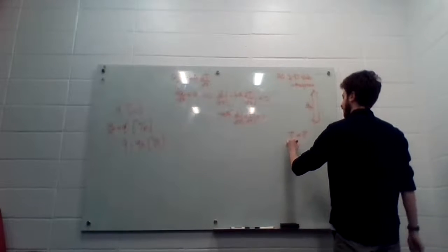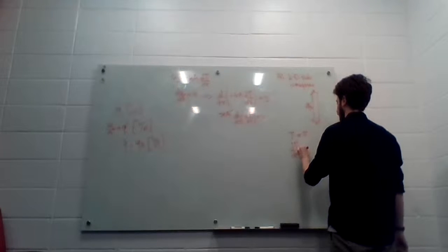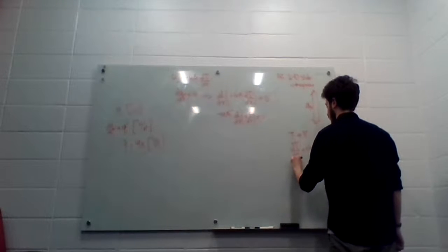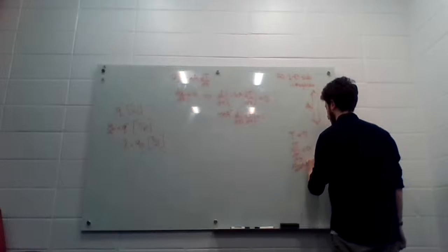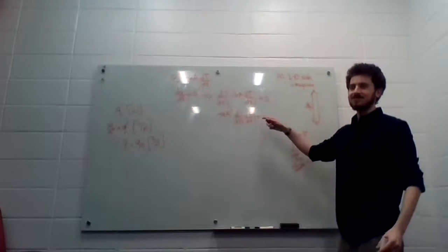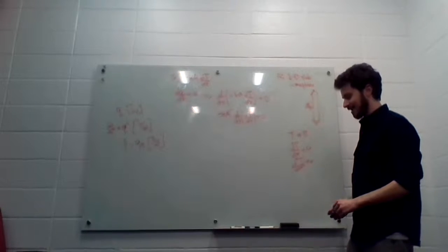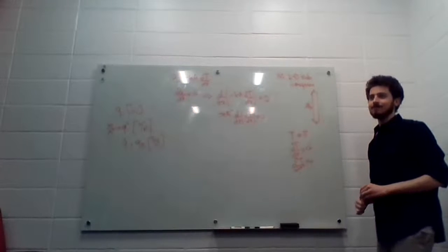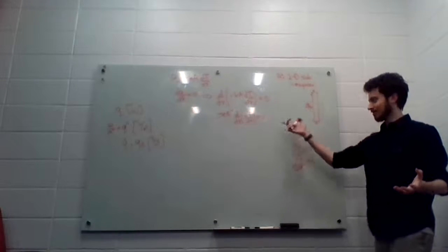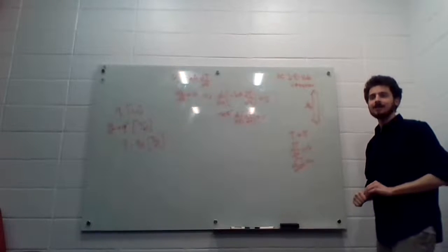And we say dT/dx. Well, does 5 vary with x? No, it's 5. So that's 0. So then d squared T/dx squared also equals 0. Lo and behold, we've satisfied this equation with 5 as the answer, but it's not the most general answer. While T equals 5 everywhere does satisfy this law, it's not going to be useful for a lot of problems.